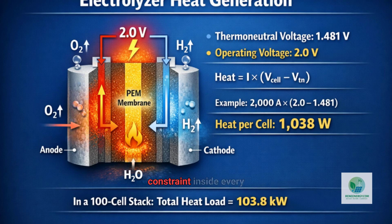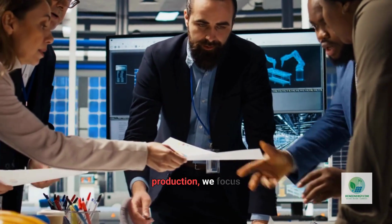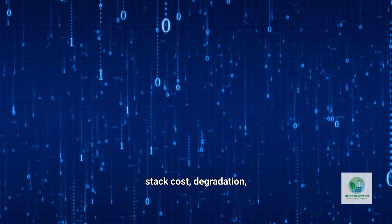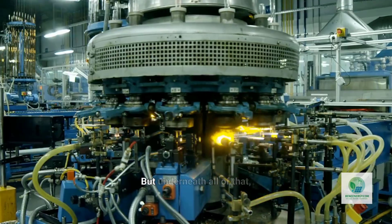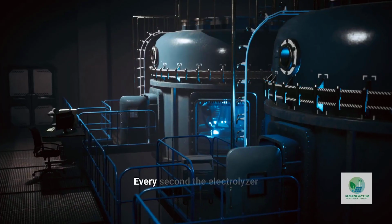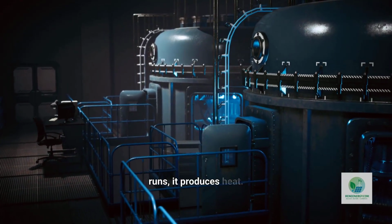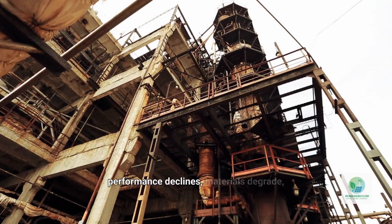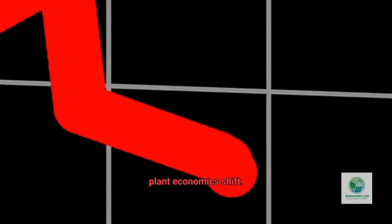Heat is the invisible constraint inside every electrolyzer. When we talk about hydrogen production, we focus on voltage, efficiency, stack cost, degradation, and electricity price. But underneath all of that, there is a continuous thermal load that never stops. Every second the electrolyzer runs, it produces heat. And if that heat is not removed correctly, performance declines, materials degrade, and the entire plant economics shift.